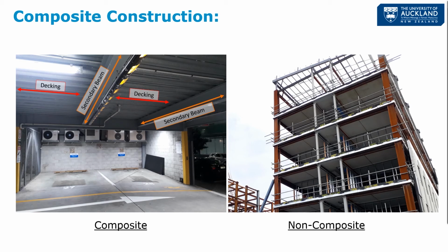Now, because the decking is running perpendicular to the secondary beam and parallel to the primary beam, it actually is not providing any composite action with that primary beam. It's really there stiffening up. And so if you think about from a tributary area and a load path perspective, it's going to go from decking, secondary beam to primary beam, and then obviously into the columns.